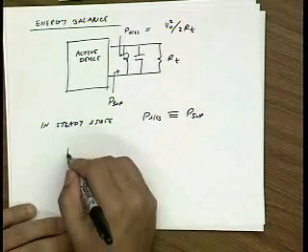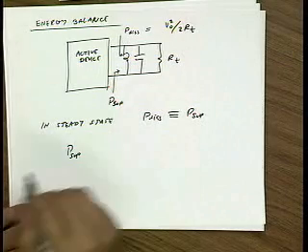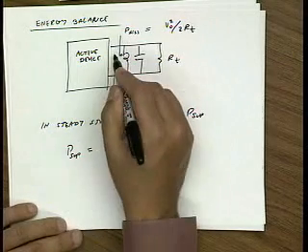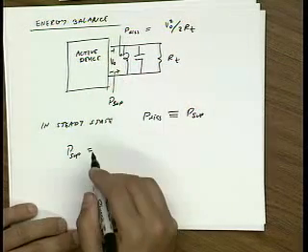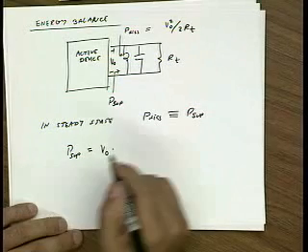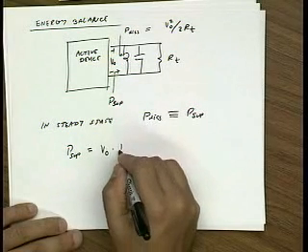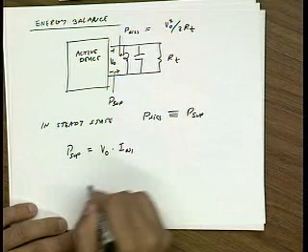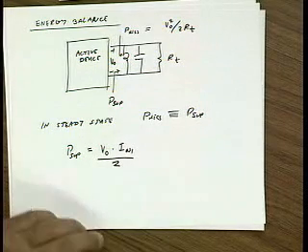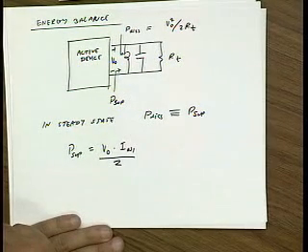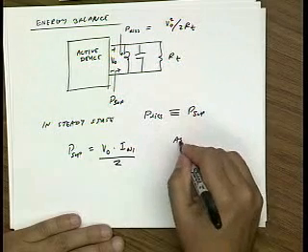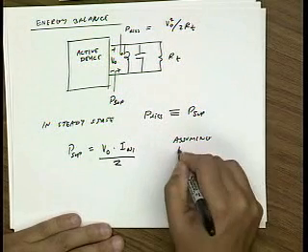So what's the power that's being supplied by the circuit? Since the voltage across here is V_O, if I knew the first harmonic current, I_omega1, coming out, this would be the power being supplied. Here I'm assuming a high Q tank.